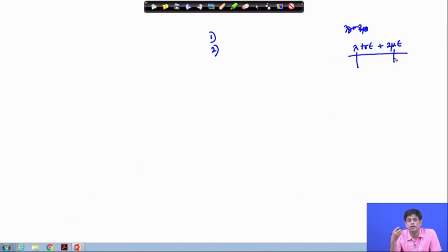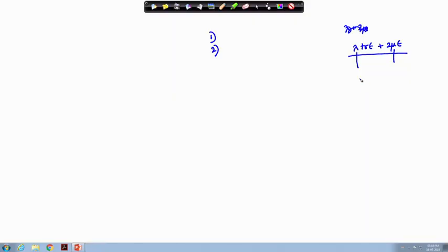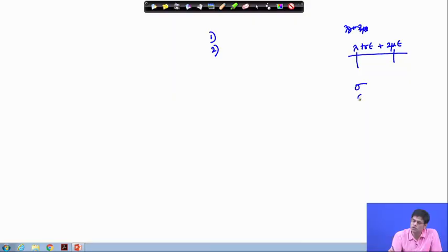For instance, if somebody wants to find the material constants for a material, how do you find them? Essentially, material constants are not directly measurable; they are derived quantities. If you measure stress and strain, then from stress by strain you calculate Young's modulus. We do a torsion test, a tension test, and a shear test, and then find the different material constants for the isotropic material.